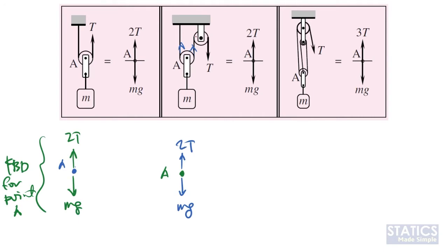Let's say for example sake, we are also interested in point B here. So how does the free body diagram of point B look? We have B. Again, here we have tension coming from the cable outward from point B, and then here we have this direction as the tension at point B. So we have here 2T, and then of course this B is being held here. So we have a reaction force coming from this point here, or this support that is holding our pulley.